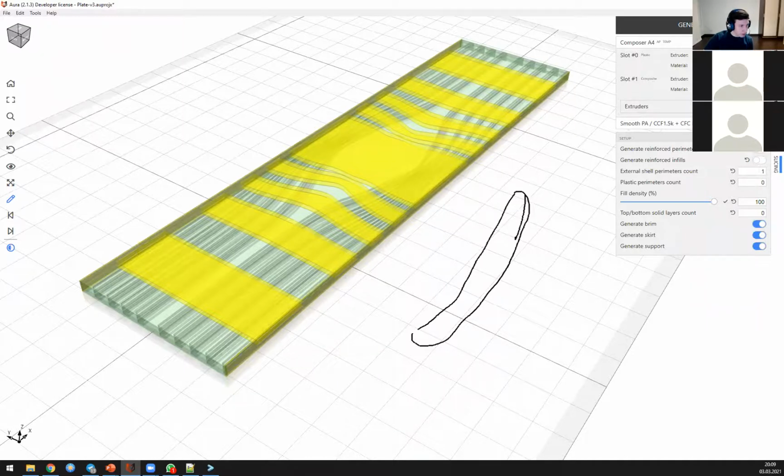Can we use continuous glass fiber or Kevlar fiber? Well, you can't use glass fiber, but we have an analog of glass fiber. It's basalt fiber. So you can choose not only composite carbon fiber, but composite basalt fiber as well. And basalt fiber is pretty similar to glass fiber, has similar mechanical properties, and the mechanical properties are even a bit higher for basalt fiber. And as for Kevlar fibers, we don't offer Kevlar fibers currently, but this may change in the future, so stay tuned.